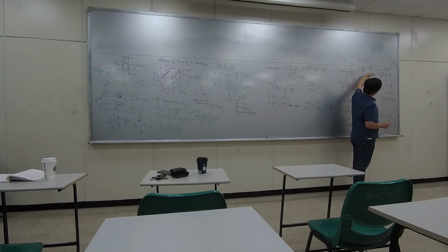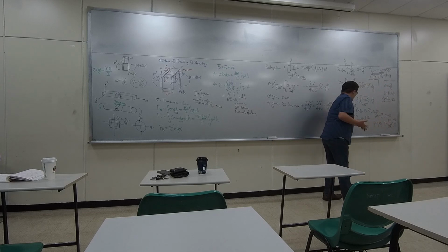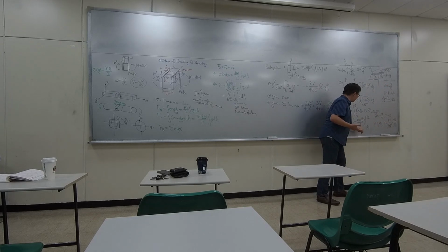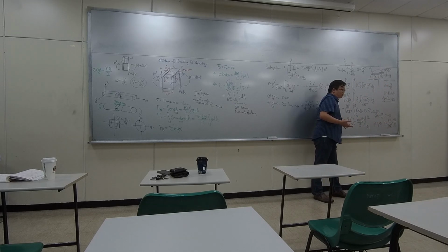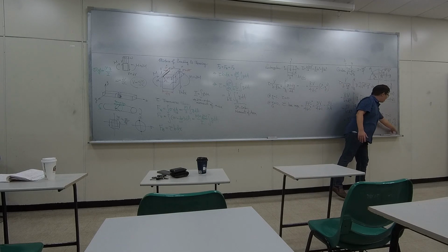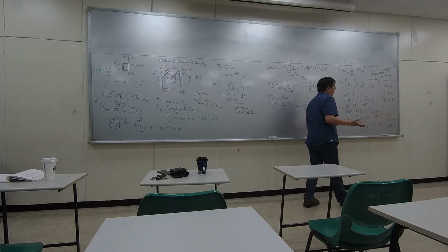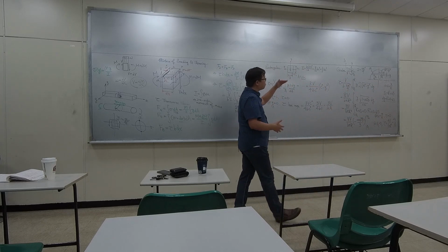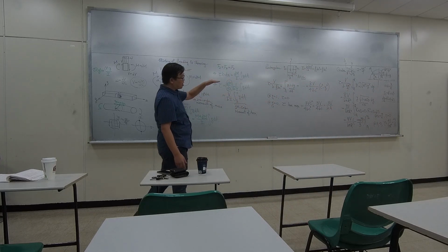If you want to study a different level, the equation gives you the transverse shear on that particular level. So all you need to do is find out on that particular level what the corresponding theta 1 is, and then plug in theta 1. You can complete this calculation. So at the end, you will get something different from 4V over 3A. It will be some other value, but that would be the transverse shear on that particular level.